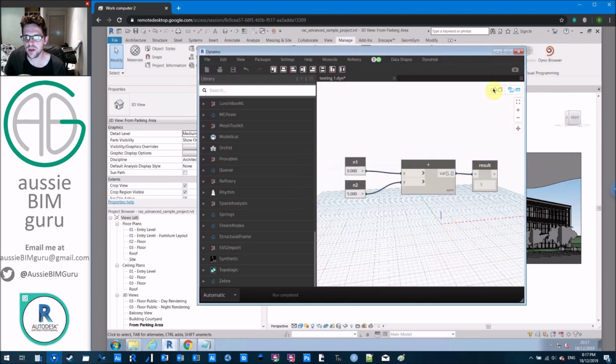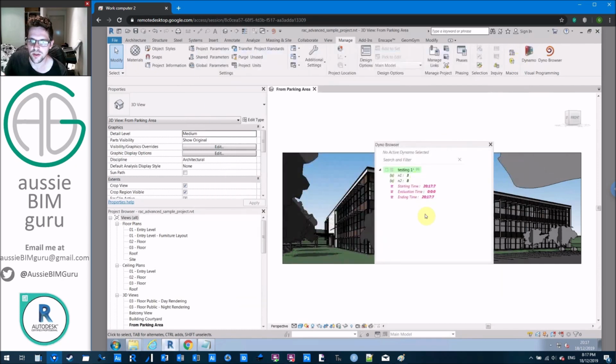I think that's it. So if you make a change to your script and you want this to update, all you have to do is right click and just go rescan workspace storage. And then we can rerun the script. It won't always restart Dynamo Core. It's only if you've just come out of Dynamo. So if I reran the script after this time, it wouldn't have to rerun. I'm probably going to not really focus on this part too often. I'm going to go through to the toolbars pretty quickly. So go on their website to check out all the basics. There you go. You can see that our output now comes out as 5.